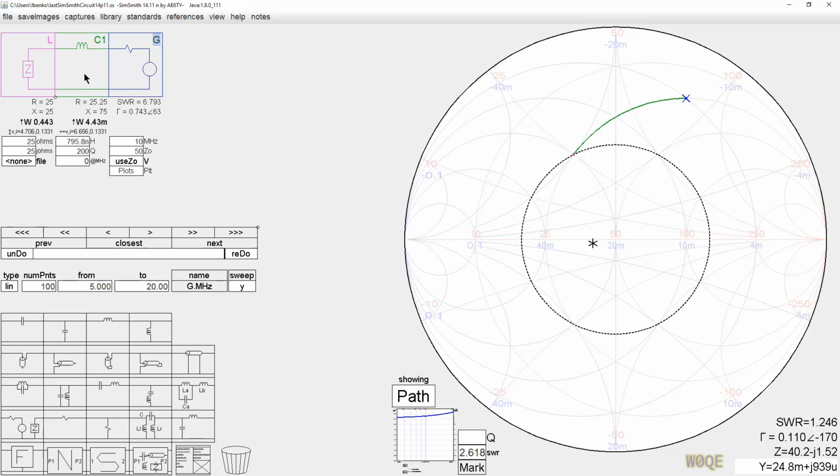We're going to do it again. Series inductor, one more time, shunt capacitor. 4 of the 10 arcs were used by rotating this component. Notice the reference designator did not change. If you really want to change it because you've ended up with this being an inductor, all you do is change it to L6, whatever. So that was 4 of the 10 possible paths you could take leaving that point.